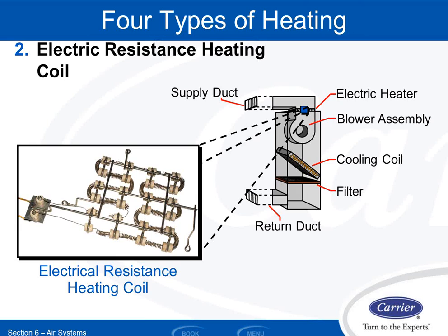So all electrical wires have resistance associated with them. As I flow electricity through there, the wire itself has an impedance and resistance, and that resistance has a byproduct of waste heat. Now, if I have a 1,000-foot wire and it's all stretched out, that little bit of waste heat doesn't really amount to anything because it's being distributed over 1,000 feet of distance. But if I jam all that wire into one space and I coil it up really, really tight, and I run a very high amperage electrical situation through it, it generates quite a bit of heat, and I'm able to heat the air substantially with electric resistance heating. So that's one mechanism I could use to heat the air.